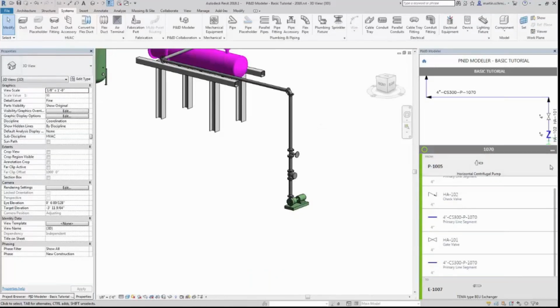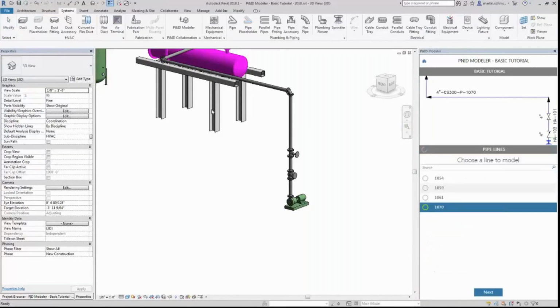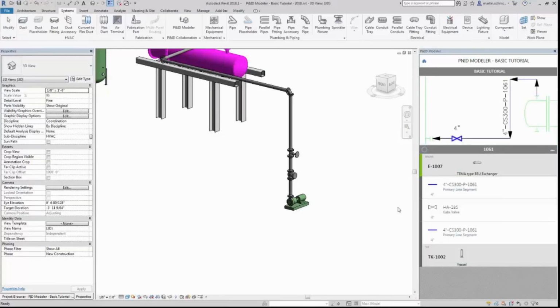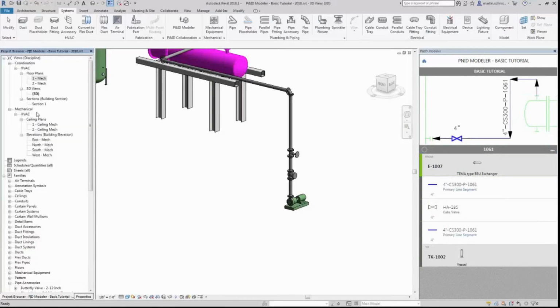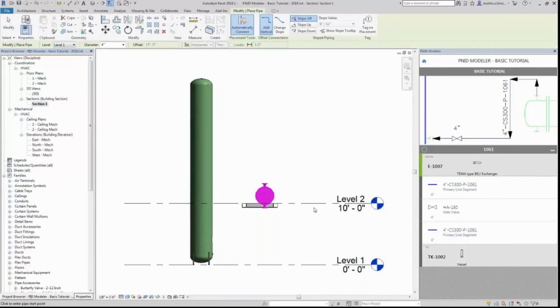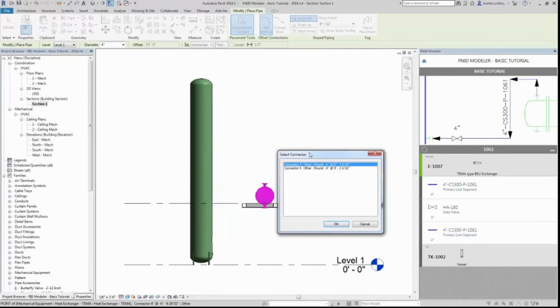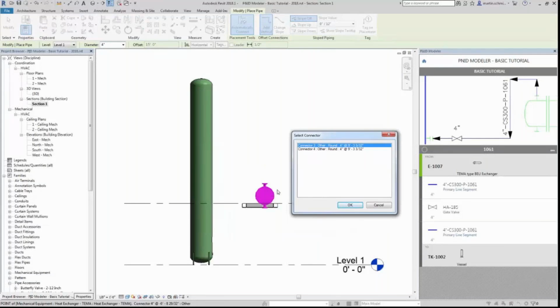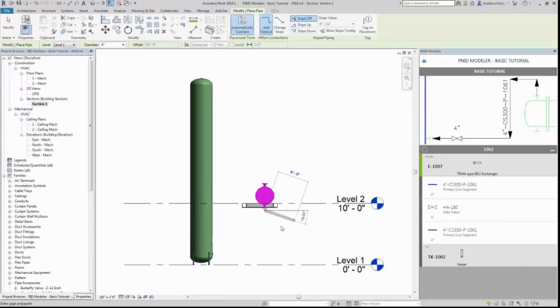And as you create the 3D model for the P&ID, or from the P&ID rather, Revit tracks which lines are complete and which are still in progress. Revit detects and displays a warning when there is an open connection or if there is a mismatch between the parts in the P&ID and the Revit model. And again, those indicators are shown around the left side of the panel there, indicators showing mismatches, as well as in the interface. So it's a pretty interesting little tool.